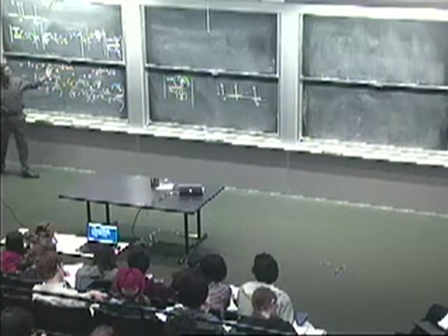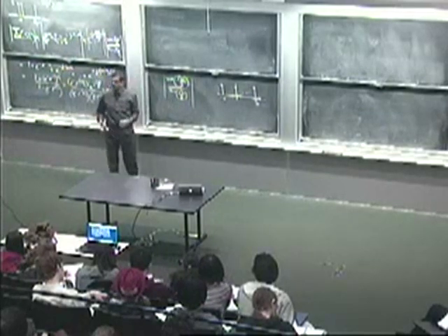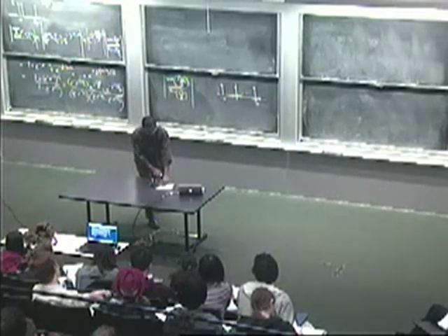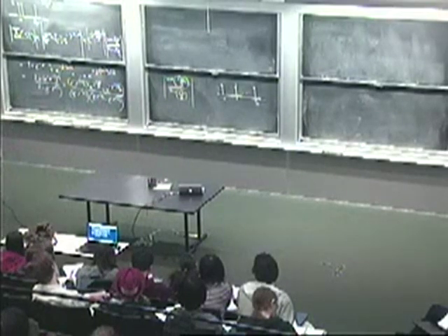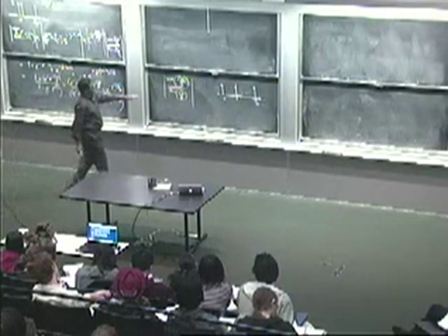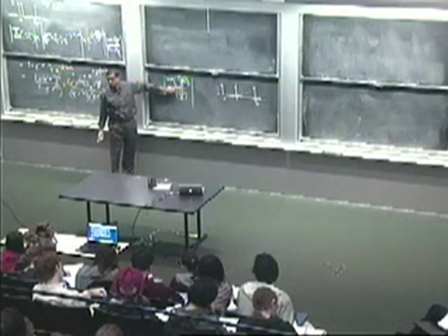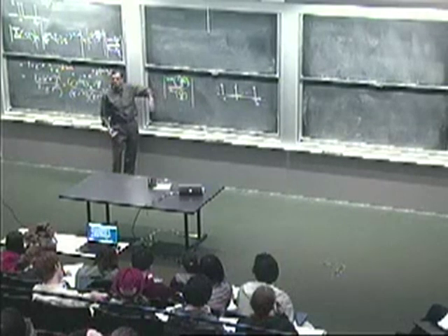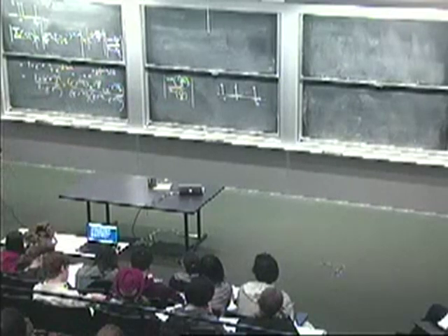But when you work it out carefully, you find that it's something close to a sinc, but one that has exactly the right periodicity. So this thing will repeat periodically with period 2 pi exactly the way it's supposed to. So it's sort of sinc-like. For small values of omega, the sine is essentially just omega over 2, and it is essentially a sinc. But when you get to larger values of omega, this thing starts to play a role.